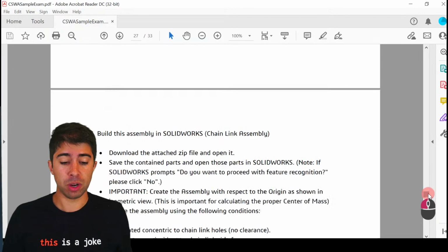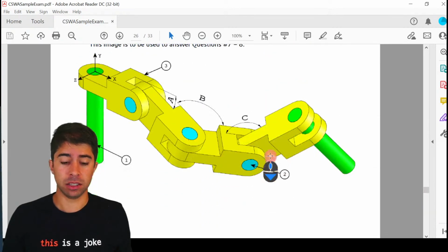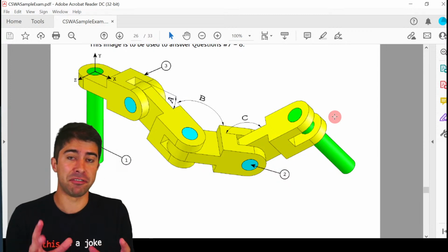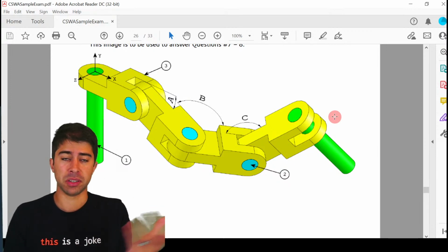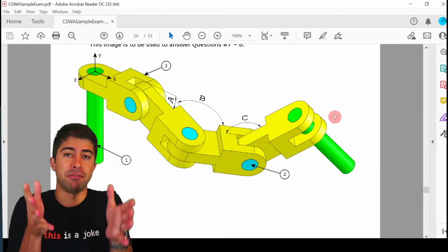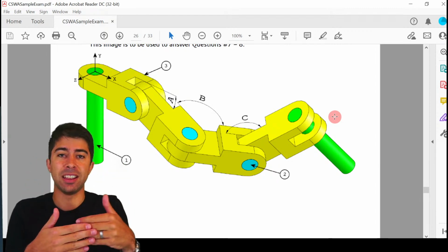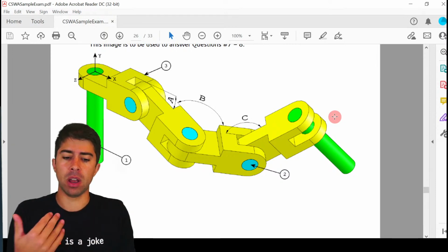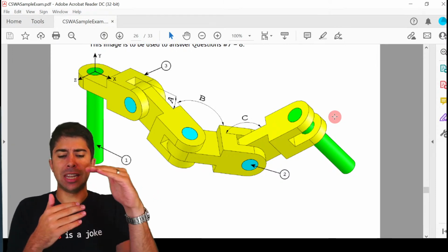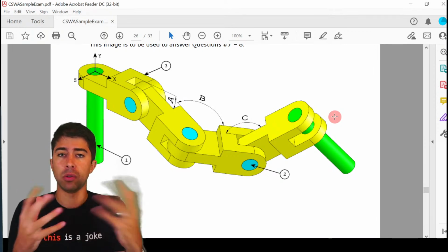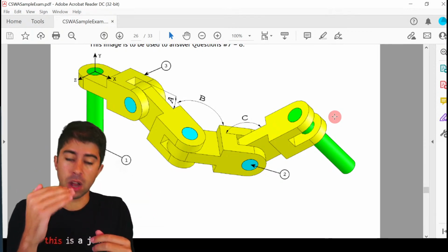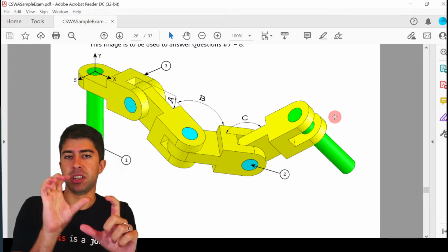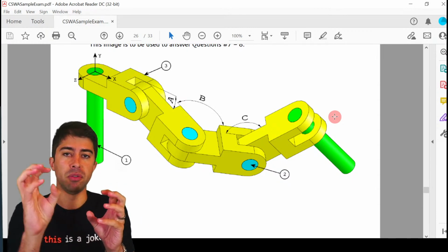The Assembly4 Workbench does get the job done in terms of doing this assembly. The thing that you just need to do, and that's different from SolidWorks, for instance, is that you need to put some forethought into where your local coordinate systems need to be, and where you need to put them to make your life easier. Obviously you can just keep them all to the local coordinate system that's given, the only one that's given when the part's created, but then it makes your life a bit more difficult because then you need to rotate it, and sort of move it, translate it.